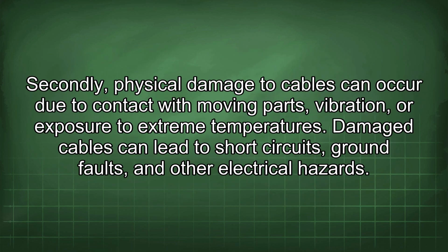Secondly, physical damage to cables can occur due to contact with moving parts, vibration, or exposure to extreme temperatures. Damaged cables can lead to short circuits, ground faults, and other electrical hazards.